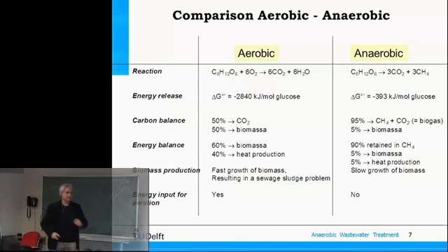As I mentioned, anaerobic technology started in the Netherlands in the 70s, and the reason for that is that at this time the new Surface Water Pollution Acts were implemented. That means that all industries needed to treat their wastewater. The polluter pays principle was implemented, so everybody needed to treat the wastewater. But in the meantime, the energy crisis was apparent. Energy was quite expensive in the 70s because of the blockage of Arab countries to the Western countries, and it meant that a lot of industries found aerobic technology too costly. And that's why anaerobic technology could be developed, and this development was pretty successful, and it indeed started in the 70s.